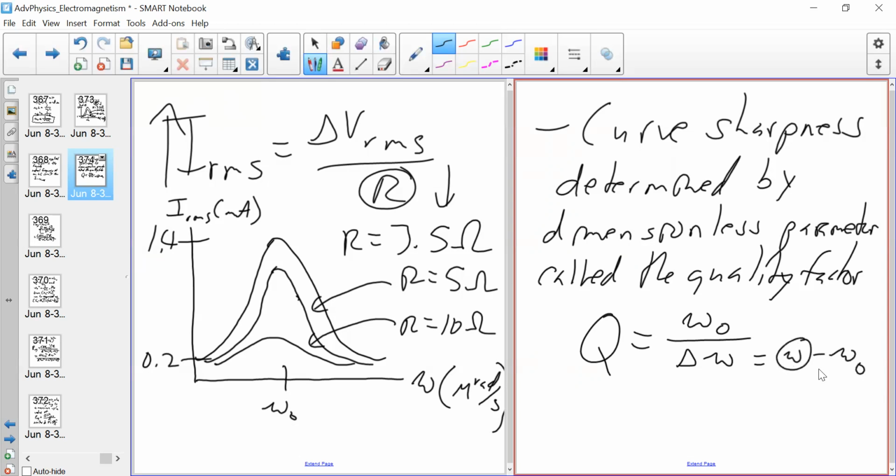So you can operate at whatever frequency, like I was saying before, but this is a resonance. Here it's not cost effective, especially when you're trying to build a radio station or radio. You're not going to be able to tune into that omega because there's too much happening with the inductor and the capacitor. But at the resonant frequency, we are, quote, eliminating the inductor and capacitor, and this makes the current and the voltage in the same phase.